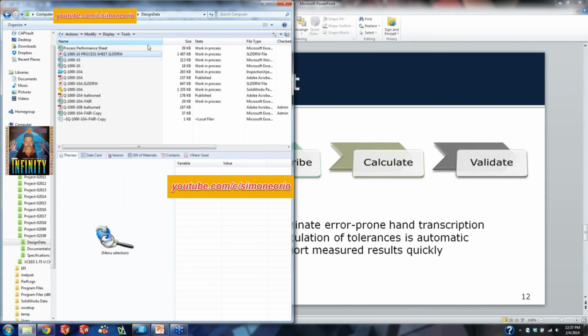And it picks up automatically on the custom properties that are built into the SOLIDWORKS file. So it knew what the part name and part number was because those were in the custom properties in my PDM system. It was all right there. Then I can give it some more basic information. What the lot size is that I'm working with, level of sampling. If I'm on normal, reduced, or tightened inspection, or what my acceptable quality level is here. So I can just pick that from a list.